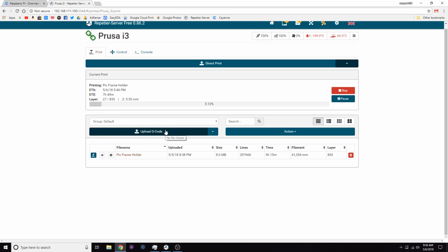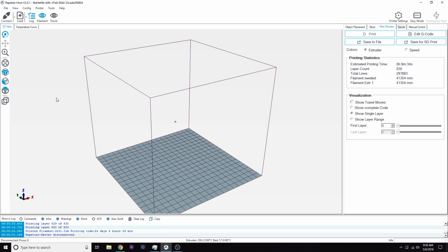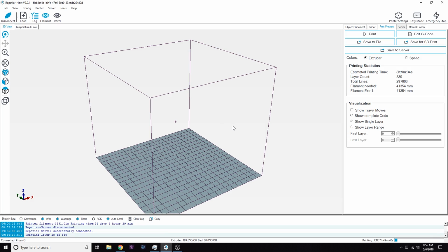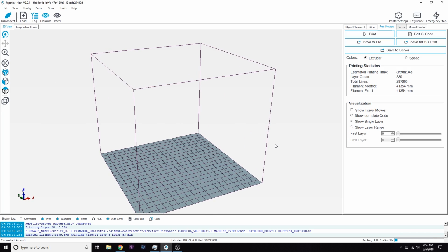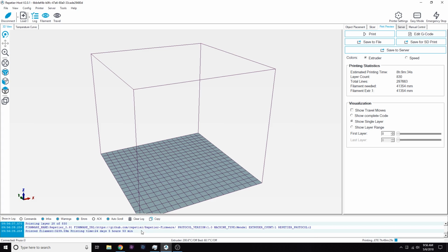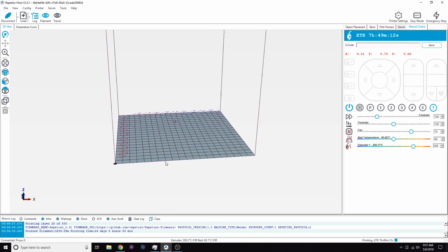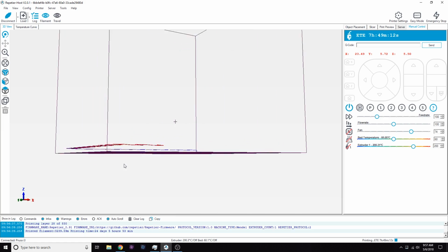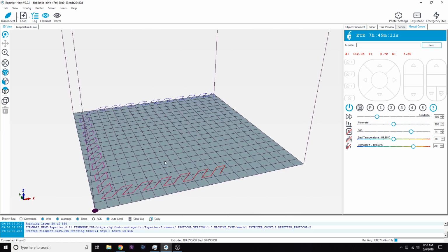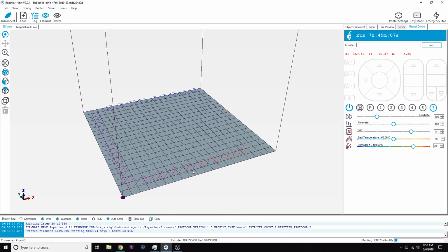You can upload G-code straight to this just like you could with Octopi, though usually what I would do is just come in here and connect Repetier Host to my printer, and you'll see some stuff pop up down here with the information about my printer. And then while it's printing I get all the estimated times and things, and we can keep track of what the printer is doing. Of course, since I just connected this, it doesn't have any information about what was lower than that, but anyway, and then this all still works too, all the controls, when it's not printing.